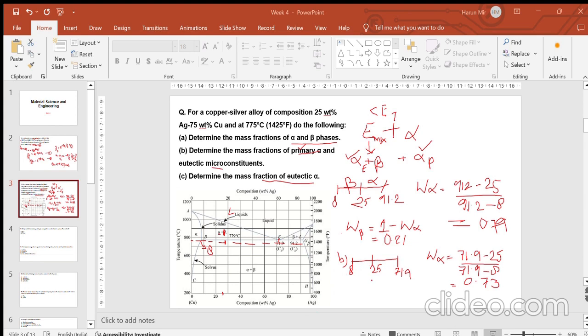If you have a certain degree of undercooling because of certain regions, because of the interface having different compositional variations, then this is your observed temperature gradient for a liquid when you have some compositional difference or non-equilibrium cooling. So you will need a higher gradient for that. So actually in this question the temperature gradient is greater than the critical gradient, then the solid liquid interface will be actually planar, right?